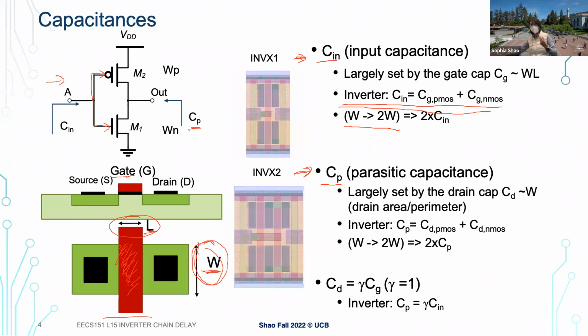So we need to charge the load, and we also need to charge the parasitic. We mentioned earlier, to get good ones for PMOS and good zeros for NMOS, we always connect the drain node to our output, so we can get good zeros and also good ones.